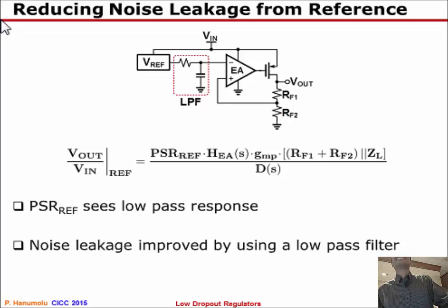I have a question about LDO regulation. My understanding is that there are now some applications that require a lot of voltage domains, and some of those voltage domains have very small power consumption. They just require an LDO to provide a steady supply. So the current consumption of that voltage domain is small, but it would still require good power supply rejection ratio. So when we go about designing an LDO for that purpose, to what extent can we reduce the quiescent current, and what are the limitations?